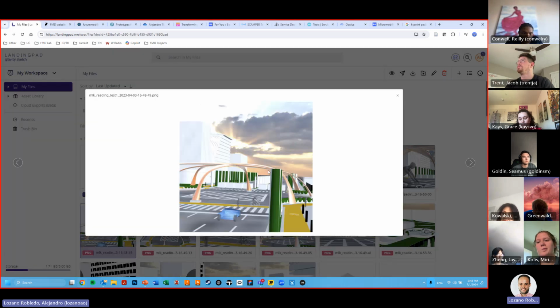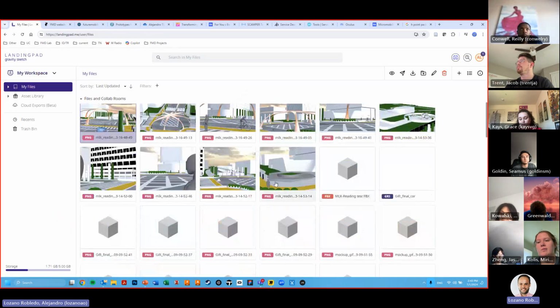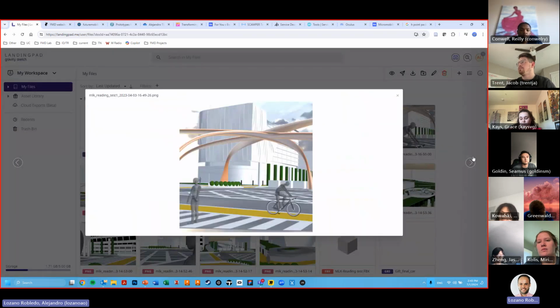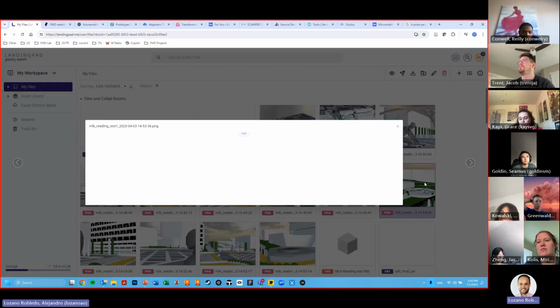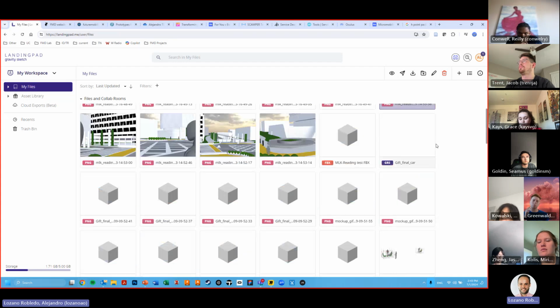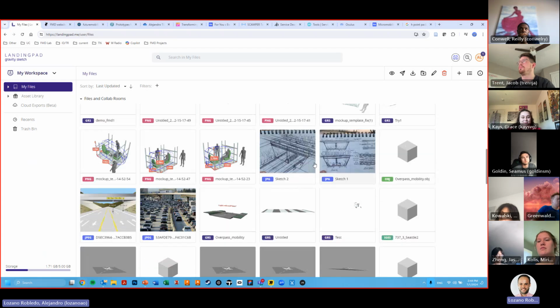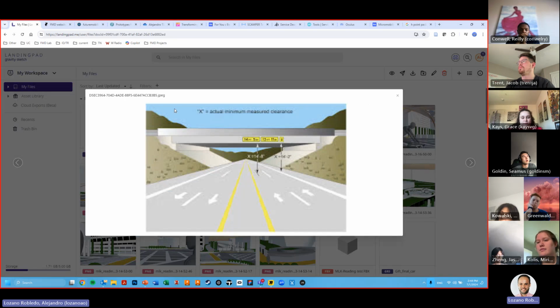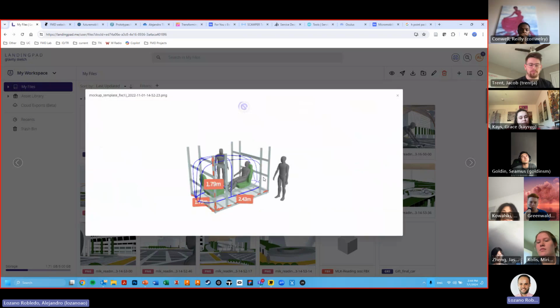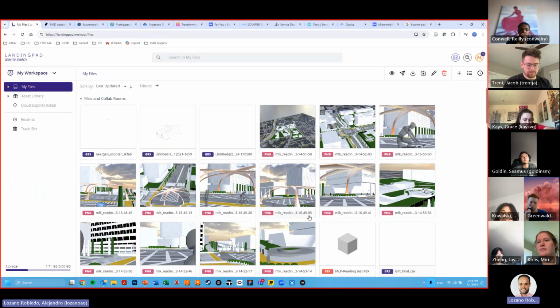You can also take screenshots from VR. These are quick screenshots of some of the recent projects I am working on for different things, very quick ones. You can export the 3D model. You can export as CAD file. So this is an FBX file that I converted in Gravity Sketch. You can export as FBX, IGS, STL, OBJ, and so on. You can import 2D images. So this is a 2D image that I uploaded from Google, but if it's uploaded here, I can open it in VR. Again, screenshot, it's extremely powerful, so leverage that.